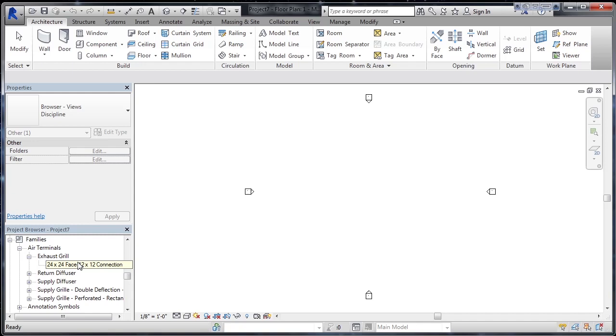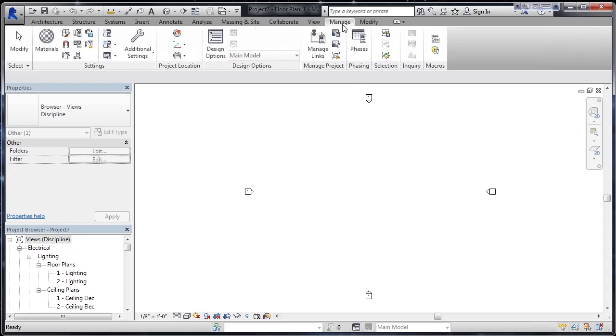the project is created. Now, some other elements you may want to set or look at inside of this project, things such as maybe you want to verify the units, or the location, or the address, or some other settings inside of this actual project. All of this can be managed on the Manage tab. So if you go to the Manage tab, you have a variety of different settings and control options to control and set the standards or defaults inside of this project.